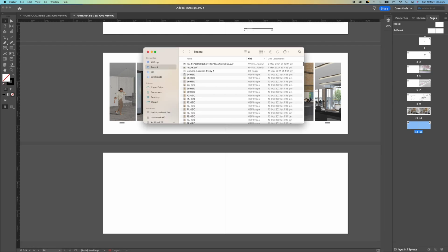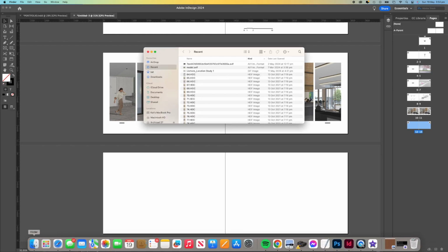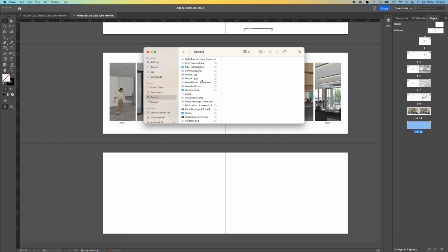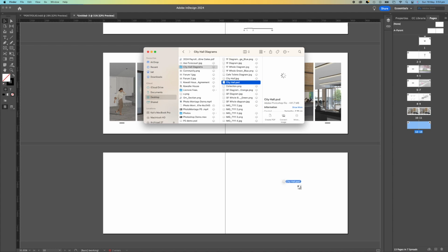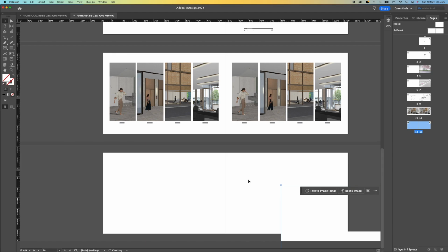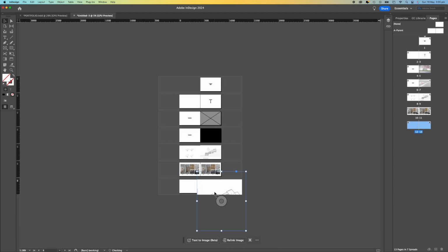Now here I'm just going to show an example of how to drop in a PSD file again, and how you can edit it by splitting up the PSD file and saving the different views over two different sheets. So I'm just going to adjust the bounding box to suit the sheet size, get it to the right proportion, and crop it.